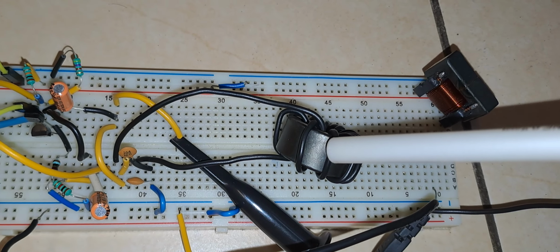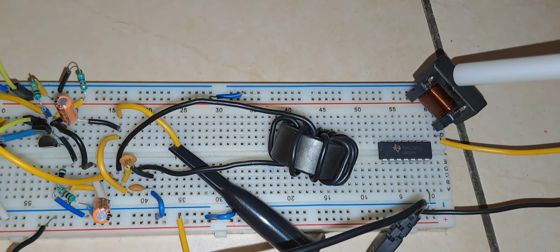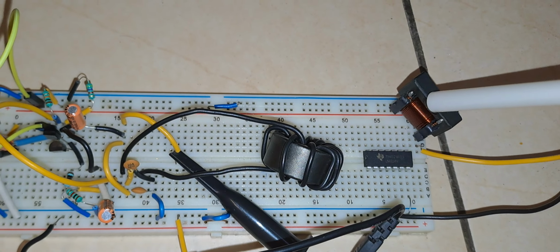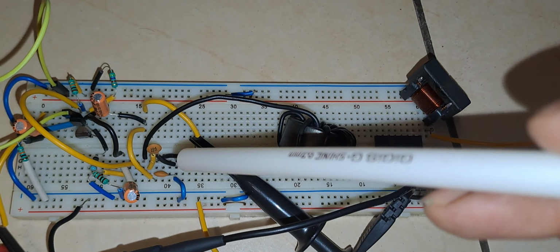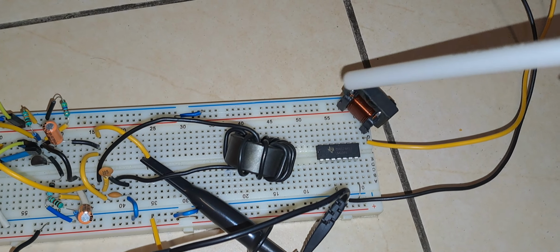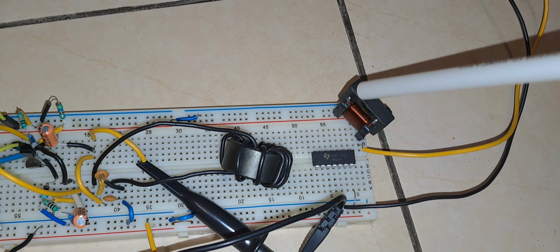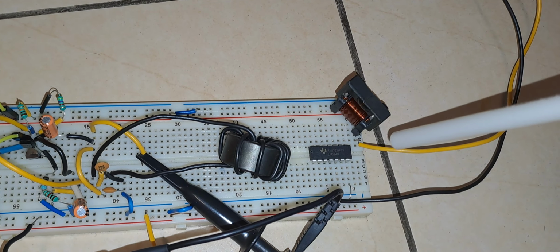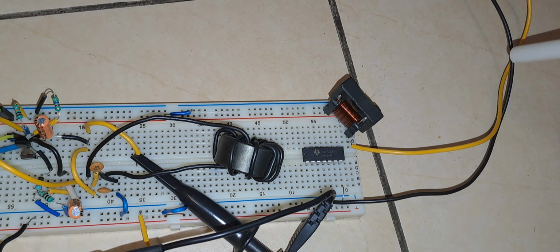This is the main coil. And here you can see this is the RF choke. This RF choke is functioning as the blocking device for the high frequency. This oscillator is going to oscillate at a frequency of 35 kHz. So this 35 kHz frequency should not flow back to the power supply. That's why this choke is blocking the high frequencies from flowing towards the power supply. In other words, this choke is responsible to maintain pure DC supply towards the circuit, and it will be blocking all the AC components towards the power supply.